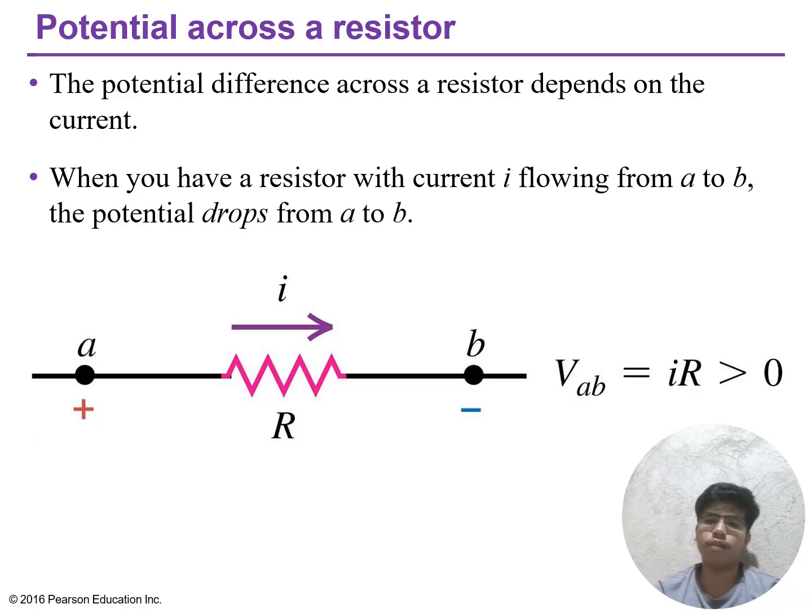So the voltage across a resistor can be written as V subscript AB is equal to V subscript A minus V subscript B is equal to negative IR, following Kirchhoff's voltage law. The VI relation is algebraic, so resistive circuits are simple. We have I is equal to V over R. In contrast, inductors and capacitors involve derivatives because their voltage depends on the rate of current change, adding complexity but enabling energy storage and frequency dependent behavior.